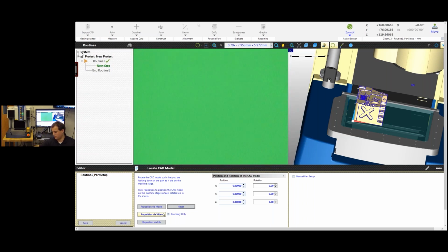But it wouldn't be very effective with something like that or my gold part here because they have varying Z heights, right? So my depth of focus is very small and shallow on a machine like this. As it goes around the outside edge of that part, it's going to go in and out of focus, and it's not going to follow that part down and up and around. It'll just stay at one Z height, which means it would go in and out of focus. So it wasn't really designed for that. It was designed for something very simple like this.